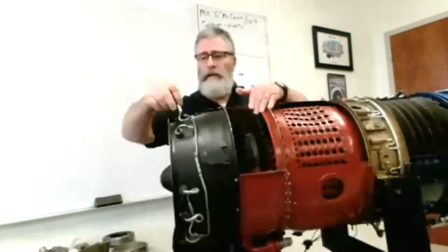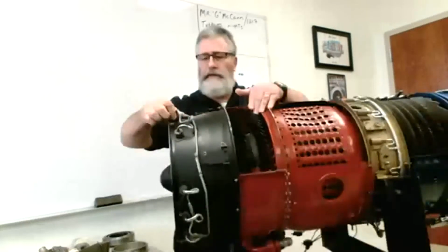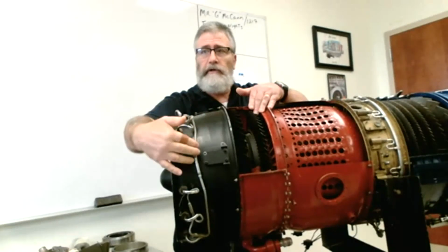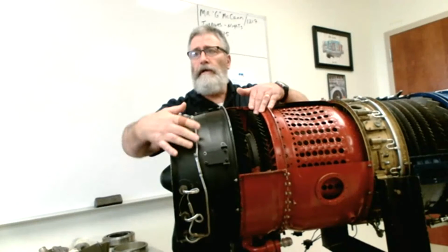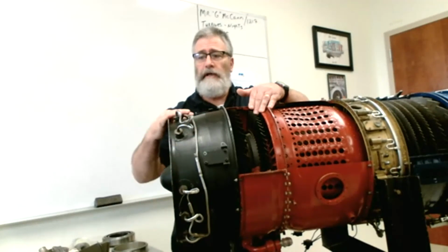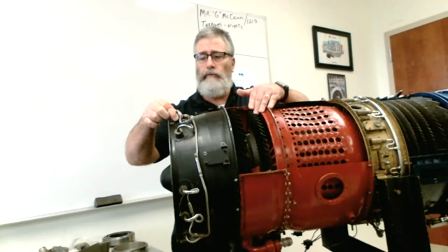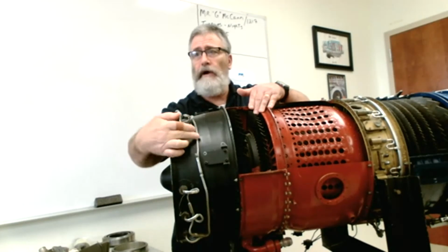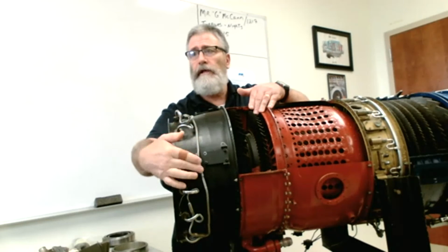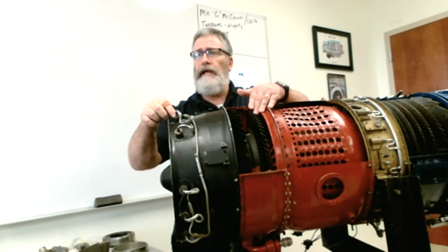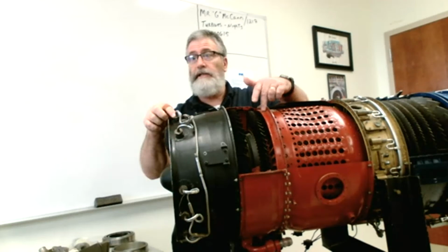All right. Now the exhaust, the EGT probes, or exhaust gas temperature probes, you can see that there is a harness here. When these are replaced, the entire harness has to be replaced. There is no way to replace individual probes, not in this system, and there is no repairs authorized. You can't splice this together in any way, all right? So EGT, exhaust gas temperature, or TIT would be turbine inlet temperature, all right?